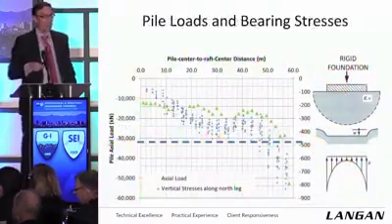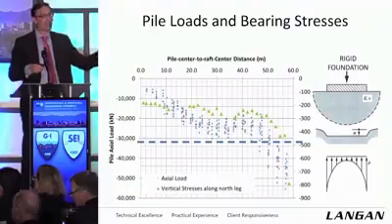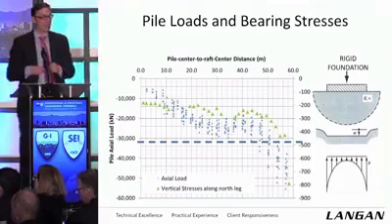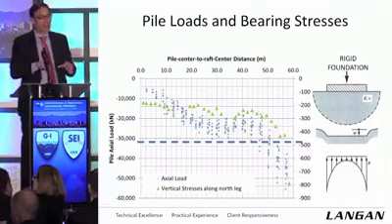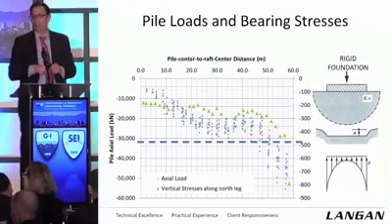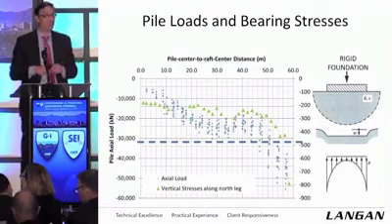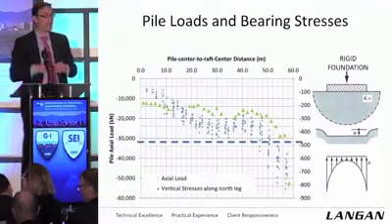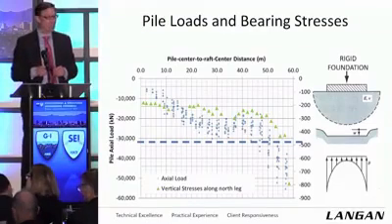We plotted pile loads. So on this one on the left, the 0 is the center line of the tower, and then 60 is out at one of the wings. And all those dots are pile loads and pressures as well. And instead of having a uniform load from center to edge, we had much higher pile loads at the edges and much lower loads at the center. So this thing is behaving like a classic rigid foundation, trying to get uniform settlement, but having a very non-uniform distribution of the loads.